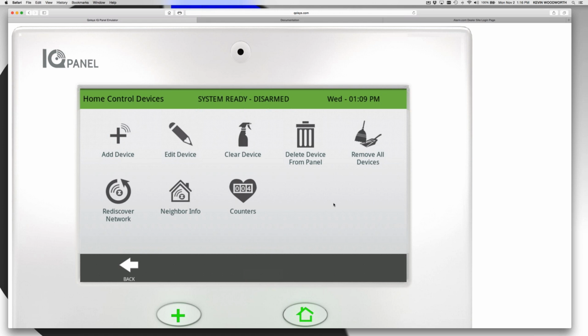It's in the 900 megahertz frequency spectrum, like 908 here in the US. It's bidirectional, so the panel can talk to the sensors and the sensors can talk back to the panel, and it's what we call a mesh network, which means the sensors can actually talk to each other as well. Z-Wave was designed to be a mesh network. That's inherent in the protocol, and because of that, it doesn't have very good range, not the same kind of range that your low frequency security RF wireless sensor is going to have anyway.